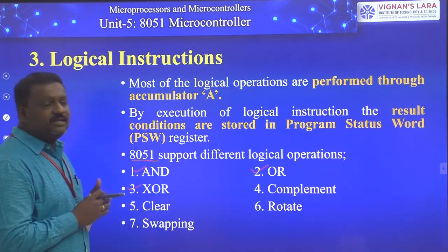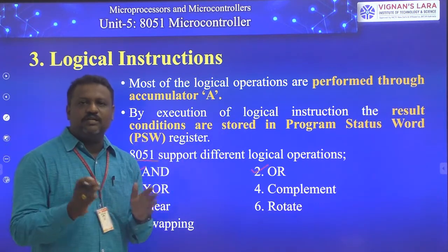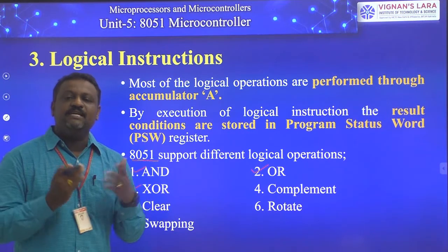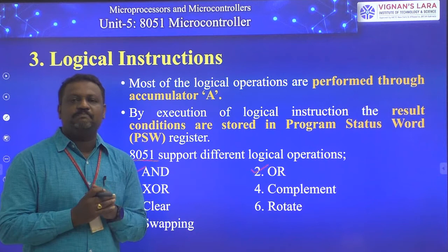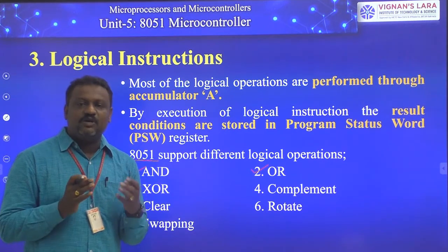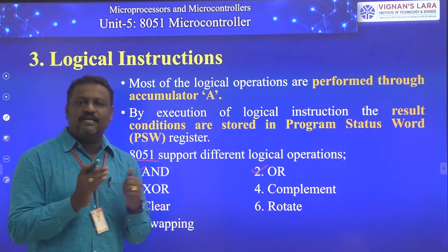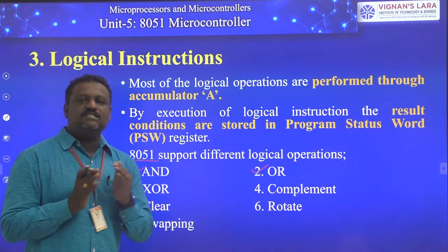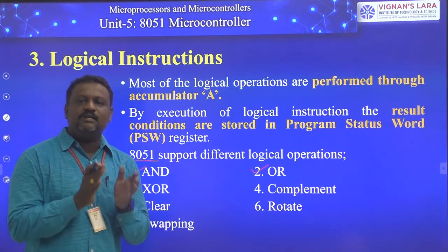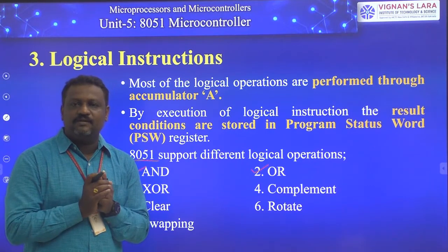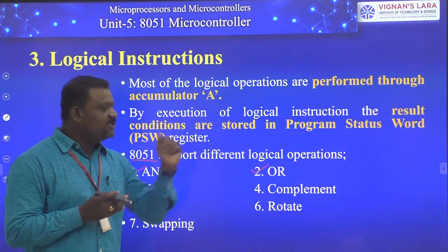Next, by execution of a logical instruction, the result conditions are stored in the program status word. If you remember the bit format of the program status word, PSW, it consists of 4 mathematical flags: carry, parity, auxiliary carry and overflow. These flag conditions are automatically set or reset based on the result we get at the output of A by execution of the logical instruction. That is the meaning of this.